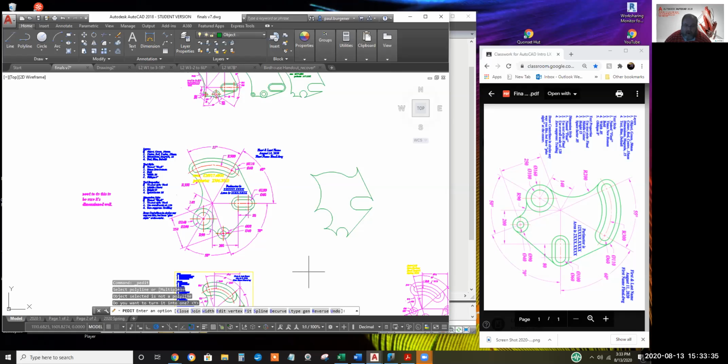Now that I've got one of the 14 pieces converted to a polyline, it's time to use the join option of the polyline edit, or p-edit, or PE enter command to weld everything that's joinable to the one segment that I just converted to a polyline.